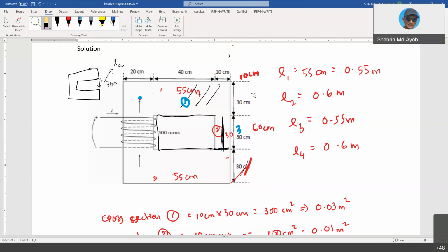So that's why when you design a power generator, you refer to apparent power. You do not design the power generator based on P only. I cannot say I want to generate P and I don't want to generate Q. That is not possible because you have numerous loads, inductive and capacitive. So your generator should be able to supply P and Q. That's why the rating of the generator always refers to the apparent power.